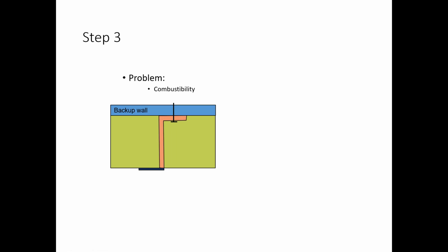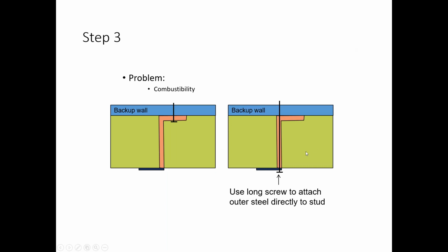The bigger issue right now with this design, to us, is the combustible connection that exists. Cladding on the outside would be screwed to this metal on the outside. And then separately, a different fastener would be fastening to the structural wall. And the composite in between, the fiberglass in between, is combustible. That would mean that your connection of cladding to non-combustible wall is a combustible connection. We thought it was a lot better and a lot more sleep at night factor to make that a non-combustible connection, which means make direct metal fastening from steel to steel to steel.